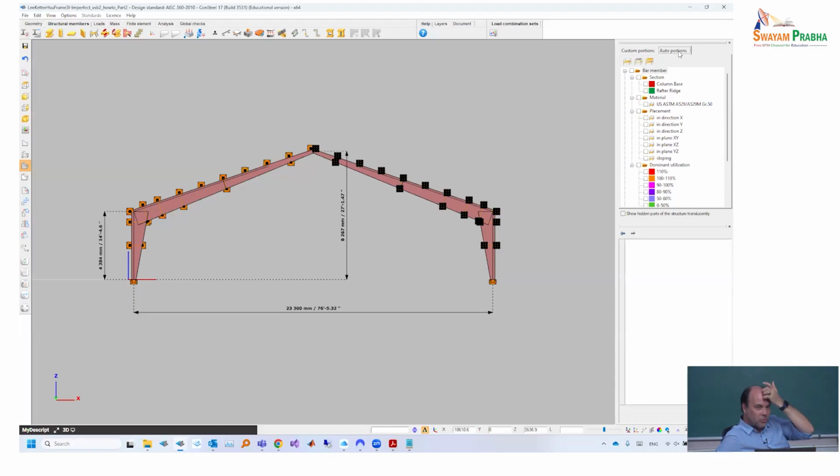In addition to such categorization, you can assign to these portions also mechanical or Consteel controlling meanings. You can create as many portions as you want. You need to give a name, and you can assign any sort of elements under this portion, and then these can be called together.